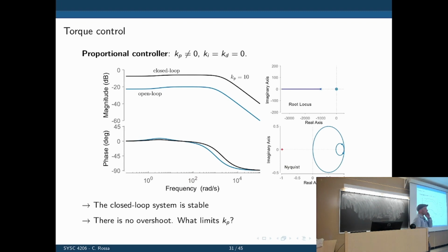I have a question. For torque versus current control, is there a reason why one is considered standard industry practice? Because it's expensive. That's the only reason. Measuring torque is a lot more expensive than measuring a current. A current sensor you can buy for $1. A 1-DOF rotational force sensor, you are looking at the 1,000 range.